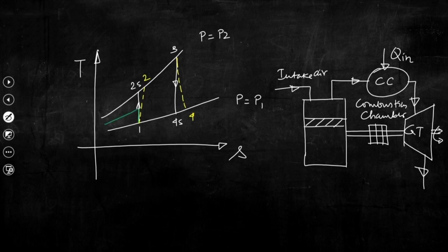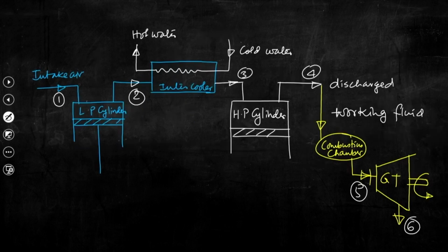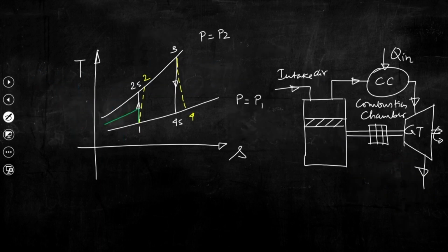So, this is the amount of rise in pressure in the low pressure stage compressor. Then what we are doing? If we go back to the previous slide, after rising pressure of the working fluid we are taking that working fluid inside the intercooler. So, the temperature will reduce, and that reduction in temperature will be at constant pressure.